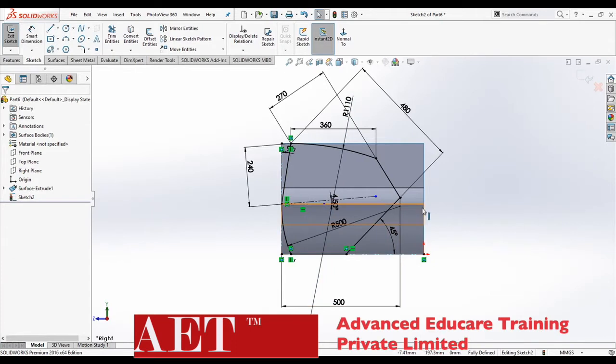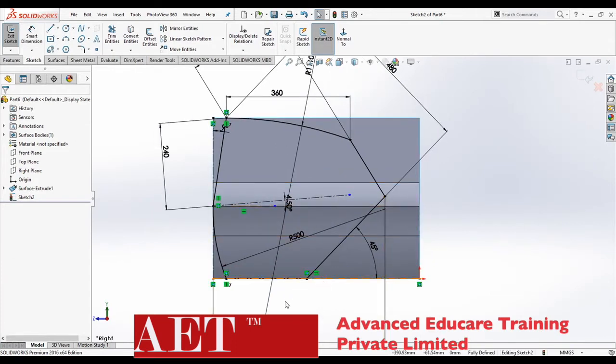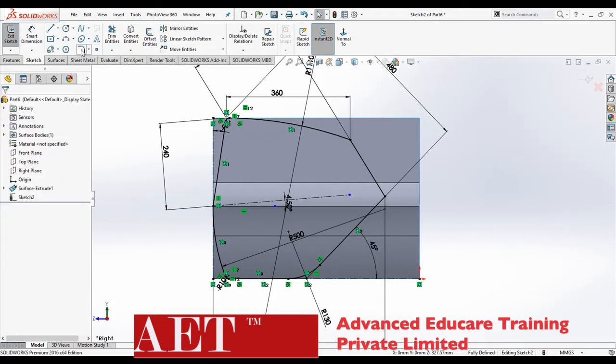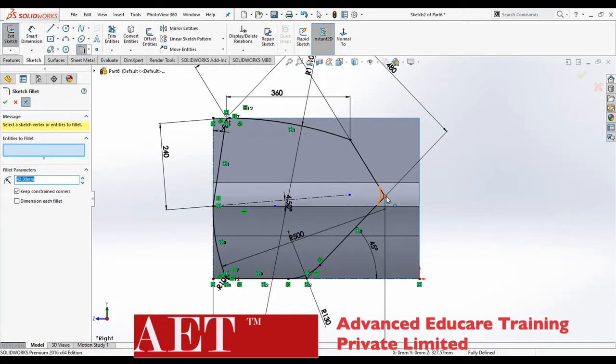Okay, now create some fillet at the sharp edges. Now take fillet and keep it at 10 mm and select these 2 points and click OK. Now change radius up to 130 mm. Select this point, click OK. Now keep radius of fillet at 42 mm and apply at this point and select OK.